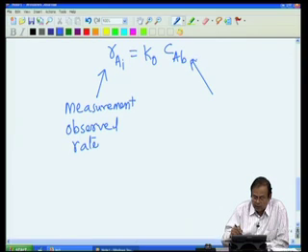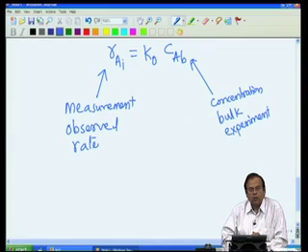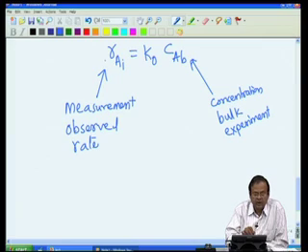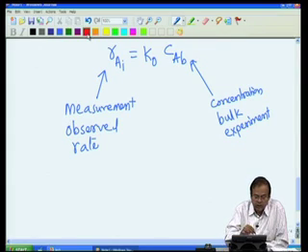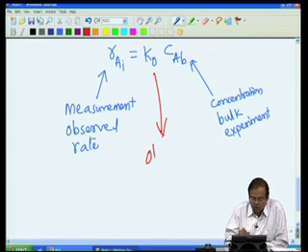This is my concentration in the bulk, which is again an experimentally measured quantity. So, when I do experiments, I measure this rate RAI for this particular concentration CAB. Now, if I do some linear fit, I will get the rate constant, which is actually the observed rate constant.